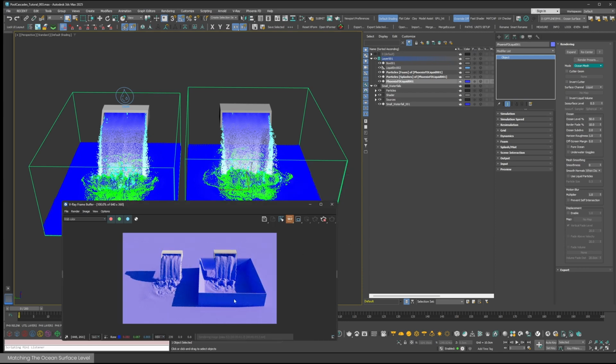And there's the merged surface. You can see that there's a problem here. I set the fill-up level inside the second container to 15%, but didn't change the procedural ocean surface level. The ocean level is still at its default 50%. I'll set it to match the fill-up level.